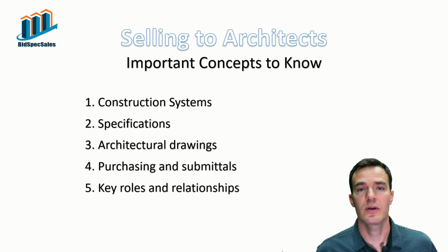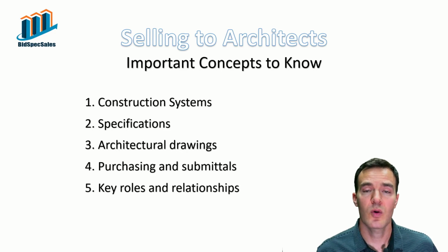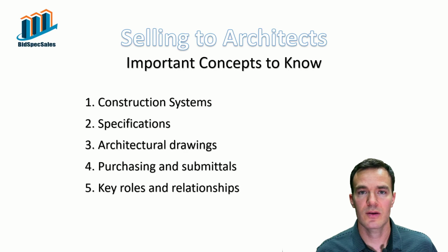You have certain lien rights, you have certain other rights that can help you get paid, of course, but also help you understand when payments are supposed to happen, what sort of time windows you can expect to receive payments, and in general, how to understand the interrelationships between the general contractor and the subcontractors, and how the architect has the ability to approve payments for work that is completed.